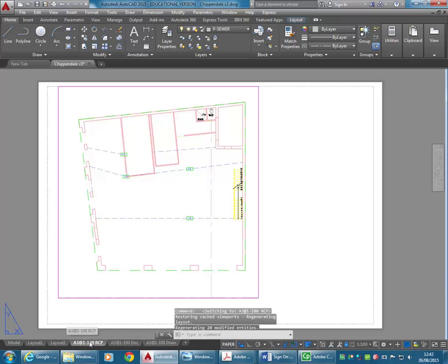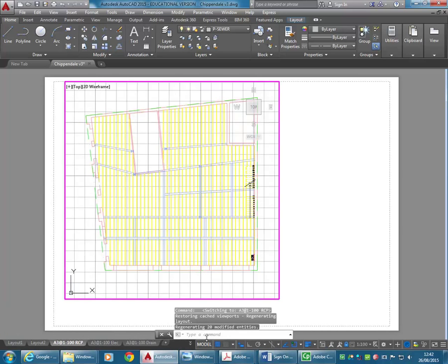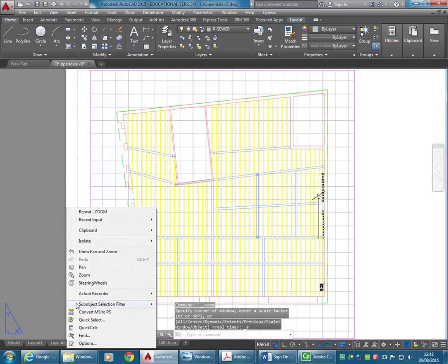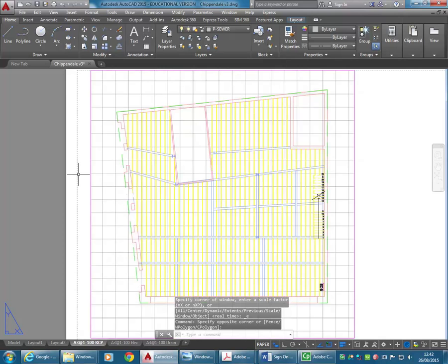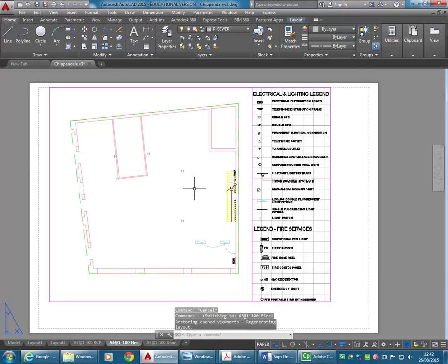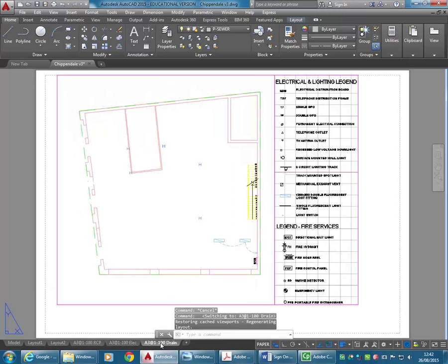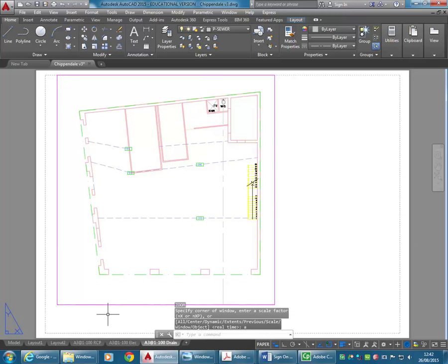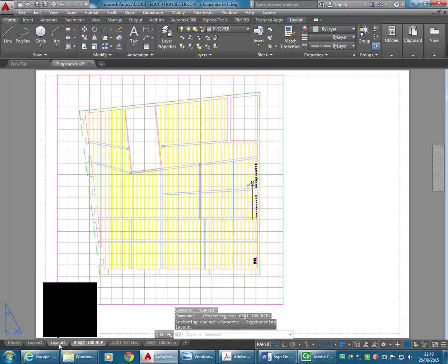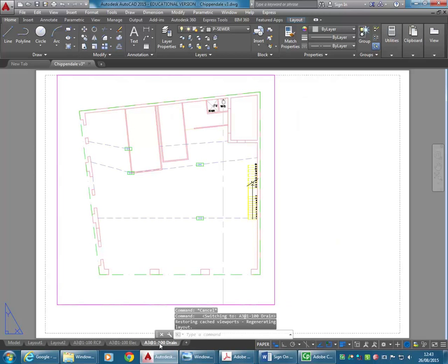And so just to prove to you that it's all in the same place, what I like to do in AutoCAD is zoom all on a sheet. So Z enter, A enter is the shortcut or quick way of doing that. And so I'm going to do that with all of these sheets. And now I can switch through each of them and notice how you can tell straight away all those plans are in exactly the same spot, which is a nice thing to have, especially when you make a PDF and it's all bound.